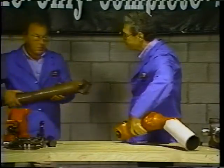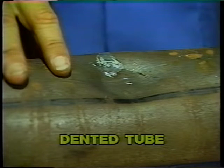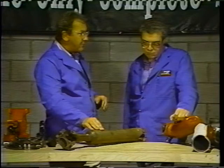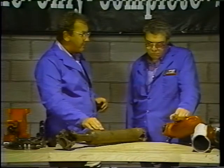I mean, this could have happened during installation or removal, or running over something on the road. A good mechanic should always check tubes for dents or throw-in balance weights which may have been sheared off. I guess the key here is being careful both in the shop and on the road, right? That's right, Bob. A bent tube will cause an imbalance problem and lead to a number of driveline failures.